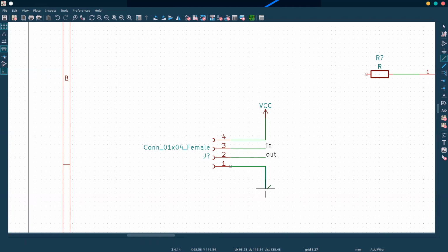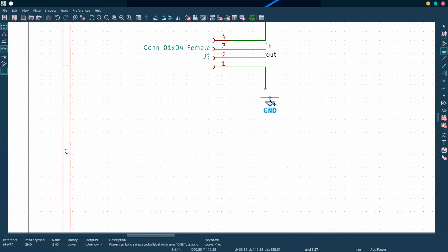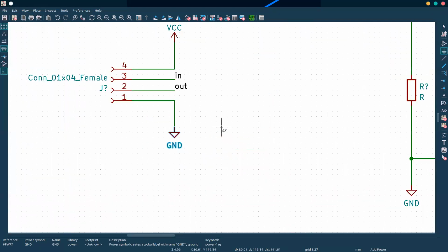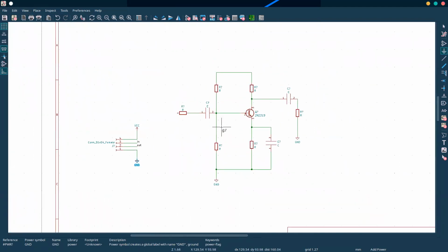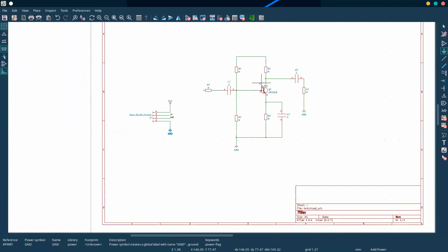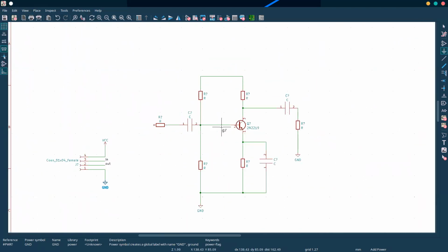Underscore one, slash four. Basically, it'll just be on the actual PCB with four holes, so you can solder whatever connector you want on there. You get to pick the footprint afterwards, but that's usually what you use. I think it's to just give you some options of what you want your connectors to look like on the schematic, because this type of connector probably generally has a certain type of look on a PCB.